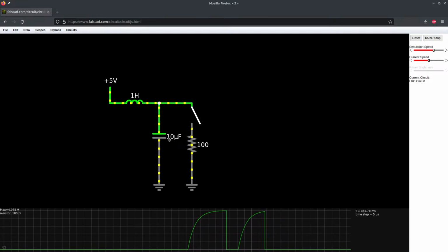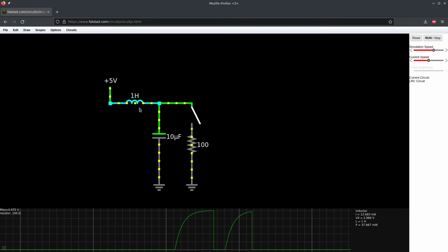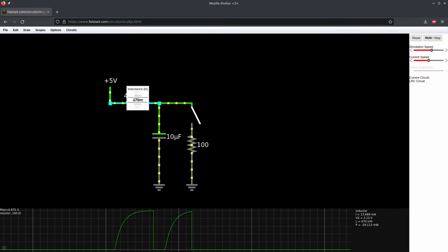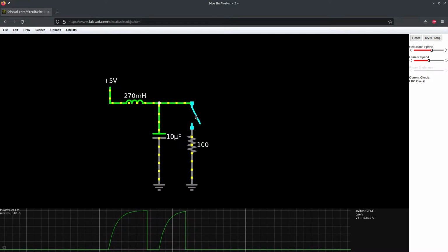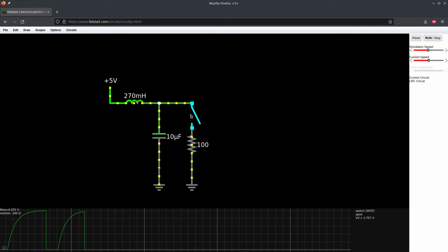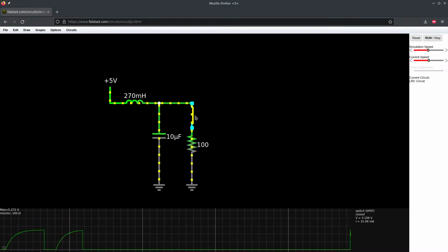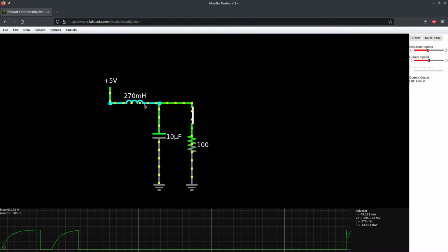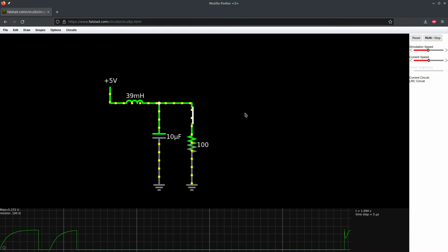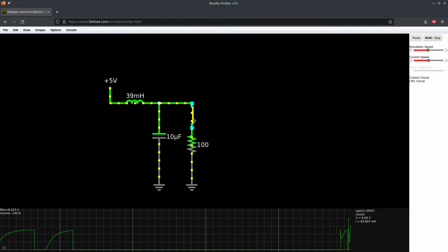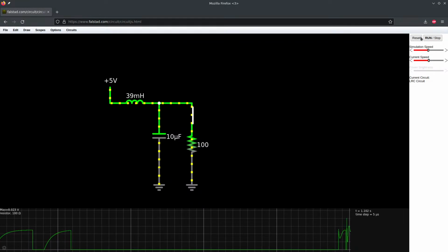This is going to oscillate for just a second in here, but this is actually a really large inductor value. When you go to charge it, it will actually much more quickly, it's not nearly this much inductance. So it will be able to take the current from the capacitor while the inductor spins up, if you will.